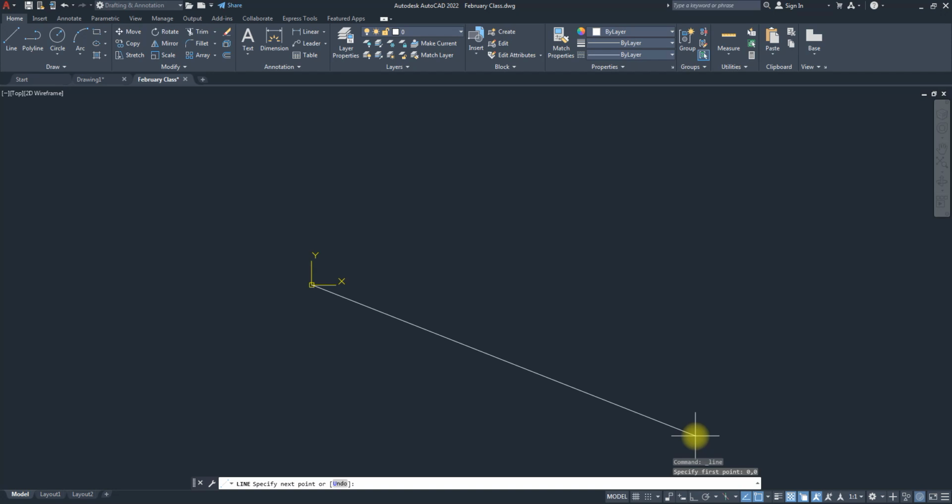So what's the coordinate value of the next point? That's why I said you guys are going to be helping me. So you say 6, 0, you press enter. Then it's asking for next point again. 6, what? 2. The next point. 2, 2. Next point. 2, 8. Next point. 0, 8. Next point. C. Enter. It creates that, but you don't see anything.